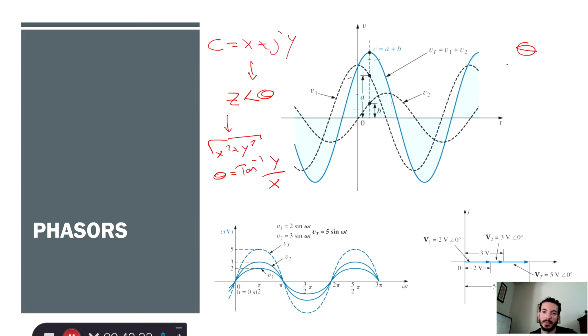So if you're able to represent the complex number mathematically, you're also able to characterize a wave as a set of complex numbers. In the case of a sine wave, for example, say they tell you voltage 1 has a value of 2 sine omega t, where omega t is 2 pi f, remember, times t, which is the time domain.